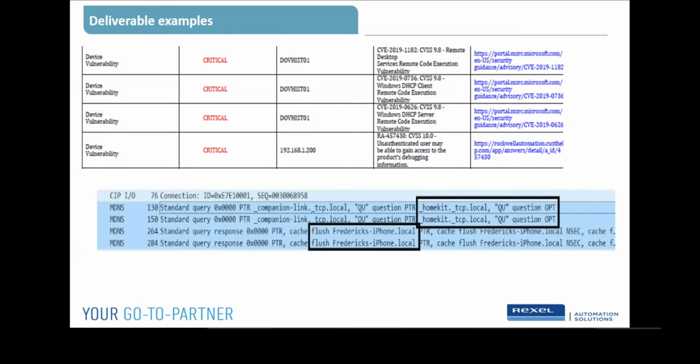But after I finally was done and was reviewing the PCAPs, sure enough, and this is only one of multiple instances showing that there's somehow or another iPhone traffic. It didn't bleed over. I mean, it is on that OT control network. So that typically is not a good thing. You should not be seeing, essentially, non-automation traffic on the network.